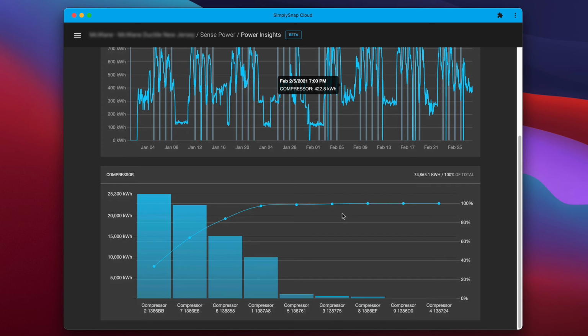Now they recently had invested in a modern control system for their air compressors. The plant manager, he was expecting that those compressors were shutting off during non-production hours. And he said he even had a guy going around and checking them. Well, you can see here are 4 of the compressors that are running after hours, which of course is costing the customer and is wasting money and energy in the facility. So through the energy insights here on the Explore page, we're able to identify those resources that need to be shut off in order to reduce energy consumption in the facility.